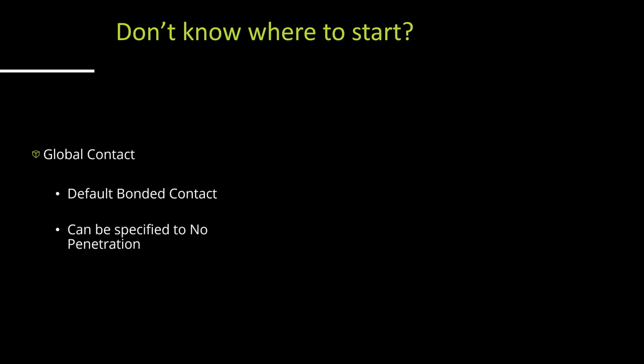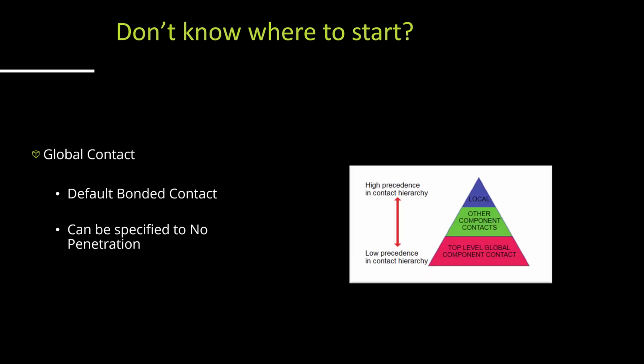Great. So cool. But if we don't know where to start, SOLIDWORKS comes in handy because by default, we just get a bonded contact at the very beginning of our setup. And this can be specified to be no penetration or with a bonded contact. These are all great things.